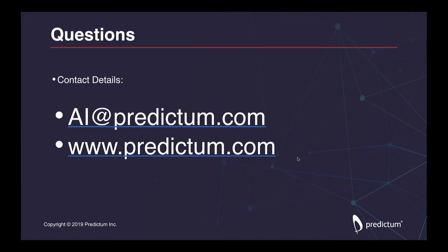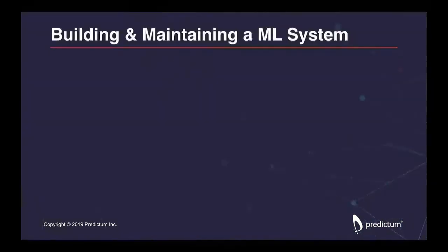So, we're trying to hit a certain abrasion, we're trying to minimize. That's what this slope here means. It's called the desirability function. And here it's saying you're trying to minimize abrasion and you're trying to maximize length. With hardness, a couple of different hardnesses, here it's saying we're trying to achieve a particular target.